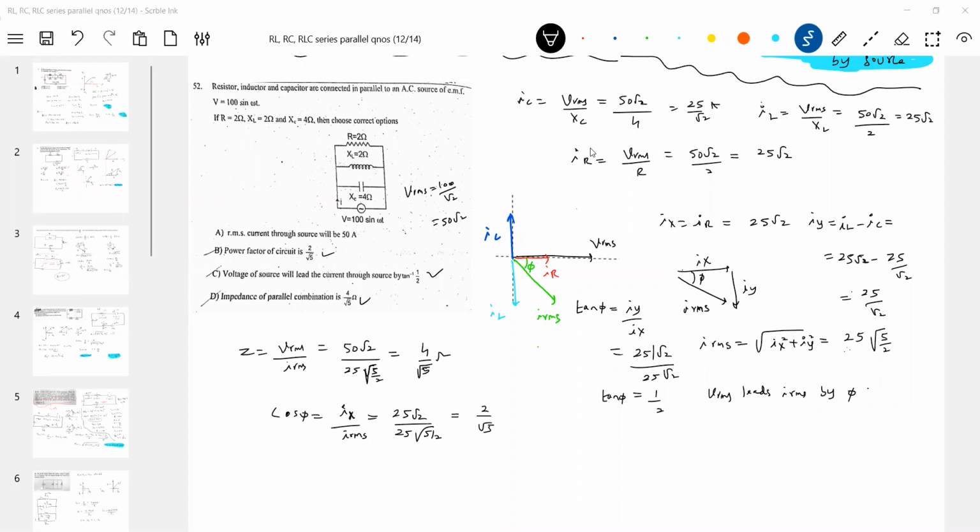How do you draw the impedance triangle here? What is the biggest problem? We are unable to draw that triangle. That's why we are coming to this. In series circuits we have the impedance triangle, but in parallel circuits we are unable to draw it because we have to take the vector sum of currents. The phasor sum of currents in different branches will have different magnitude and phase.